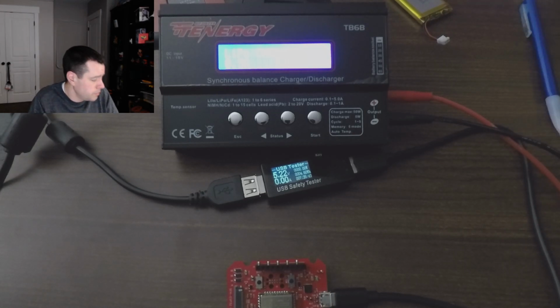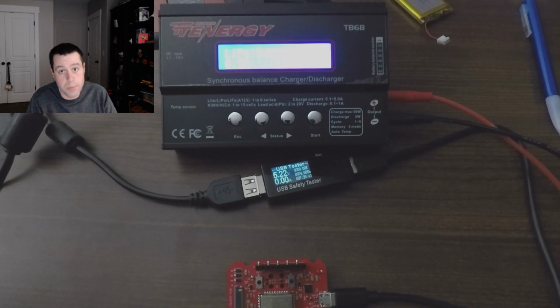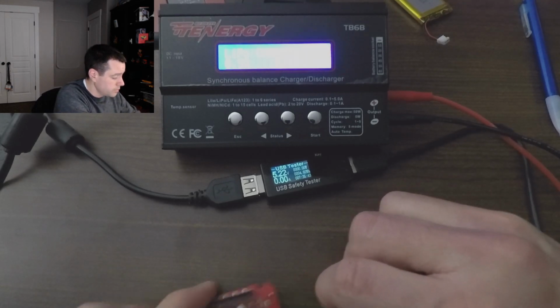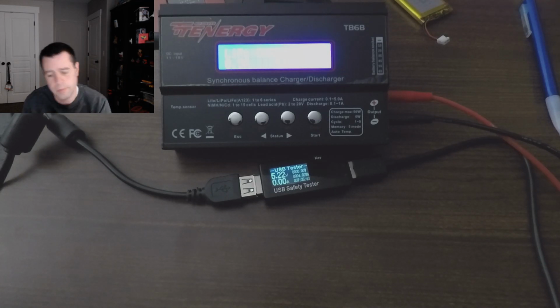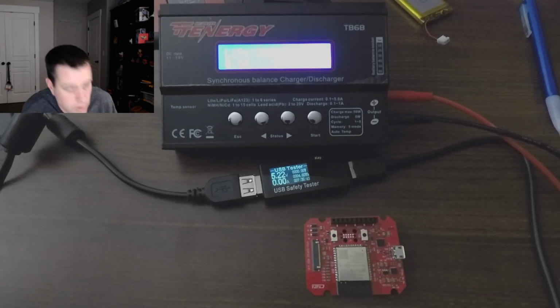So, what did we learn? The charge current's correct. I'm missing 20 milliamps. I've lost 20 milliamps somewhere. And versus charging the battery and not, why would that be? Where would that current be going? Now, I did want to look at our data sheet here, and let's look at the current that it consumes just to do its job.